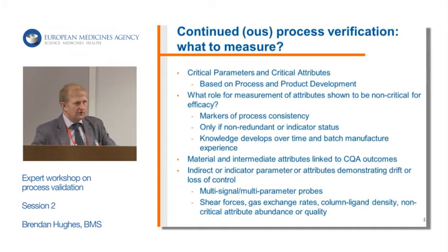And then finally, again, tipping our hat to some of the technology changes, I know some companies are looking at probe systems which can look at a very wide range of materials in a reaction or in a bioreactor or in downstream, and begin to draw correlations between certain signals and process behavior. So as we move towards a system for biotechnology products where we can actually exert continuous process verification, some of those technology breakthroughs will be important.